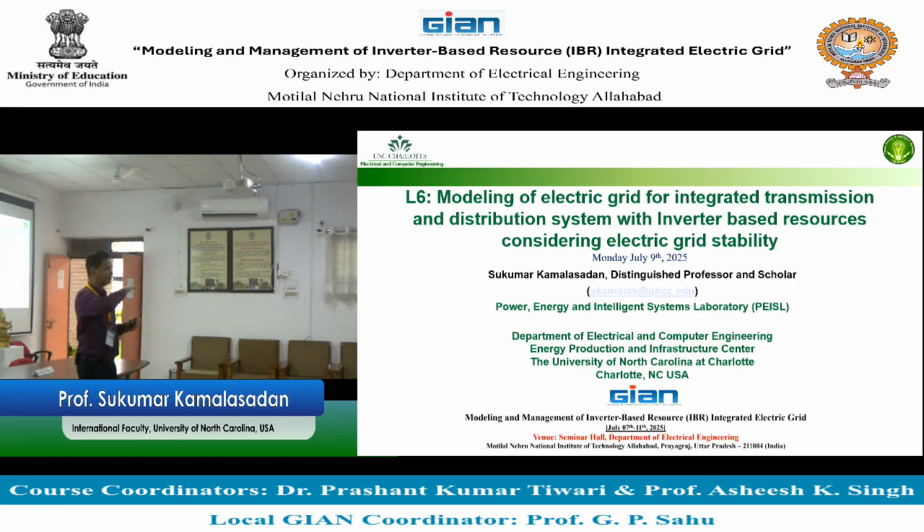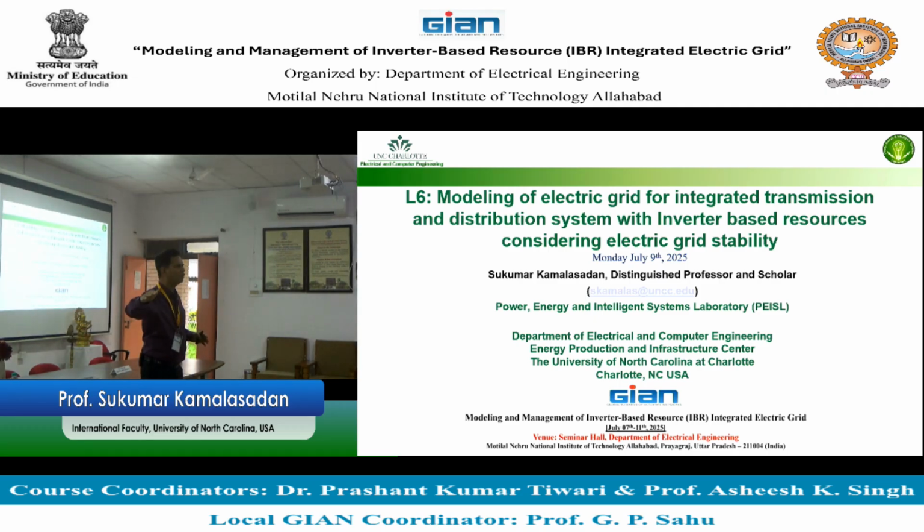The load variation is very slow varying load, right? In the morning you'll have a peak, maybe sometimes, and in the evening you'll have another peak. Depending upon the duration of the weather, you'll see the changes, right? Such power flow study used by utility, we call it snapshot power flow study. Remember yesterday we talked about snapshot. Snapshot meaning one time you do the power flow, next time you do the power flow, and then run as a snapshot study, right?